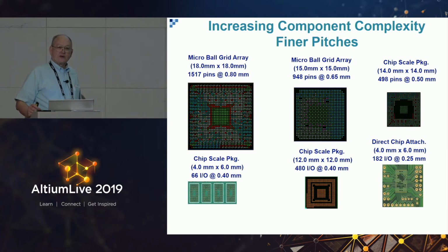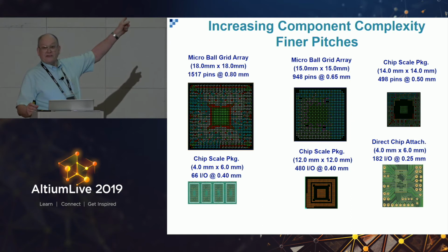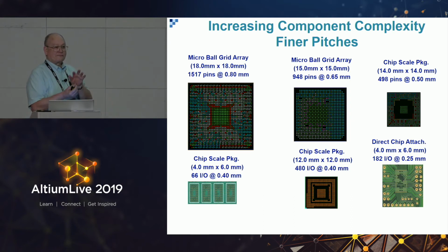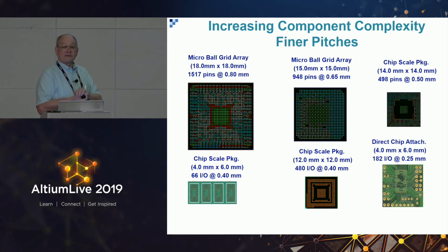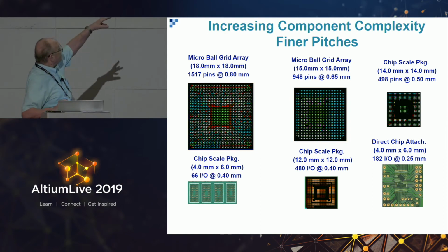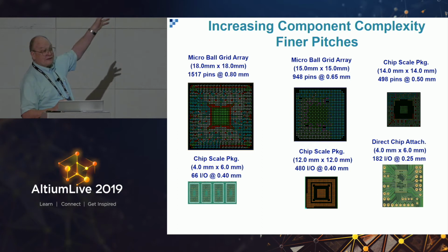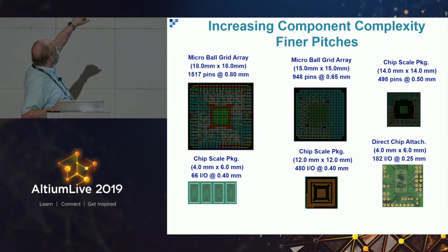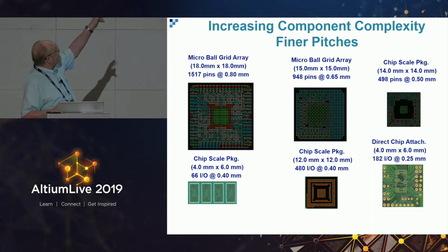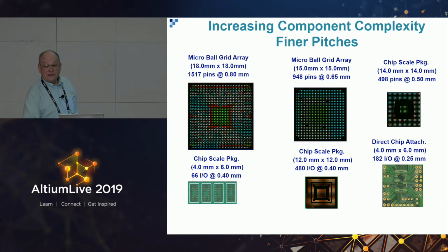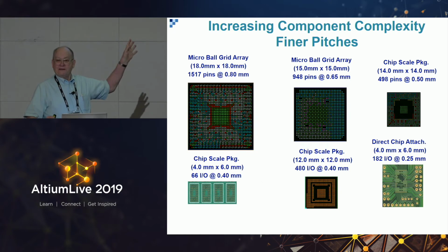The Opel for the last 20 years has had technology greater than the military or space has had because they take the engine control and put it right on a very thin printed circuit board. And it's more reliable than using a ceramic, hermetically sealed military package. I've seen the data from General Motors. And 0.4 now is pretty decent. These 0.4 are now 0.35 and 0.3 millimeter pitch. And there's some 0.4, 0.8 millimeter, nearly 1,000 pins at 0.65, 500 pins at 0.5. Like I said, this is 20 years ago.